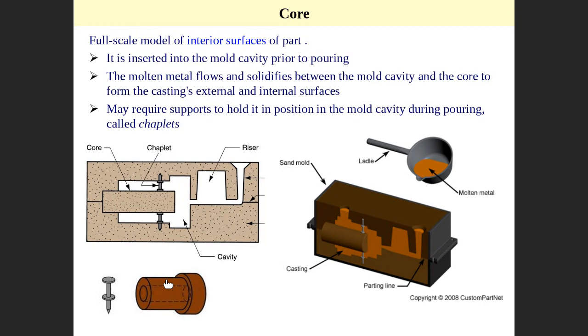Someone might say, okay, remove it and just do machining. But sometimes the dimension is very big, and then you lose a big amount of material. In this case, you must use the core. So it is case by case. If the dimension is small, then probably you can remove the core and use cutting or machining to drill the hole inside. But if the dimension is very big, or the whole part is big, then the core is essential and you must use it.